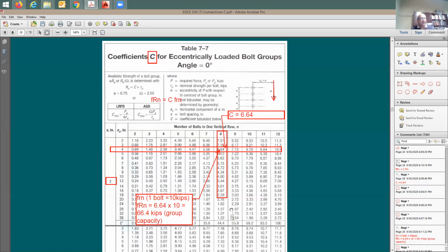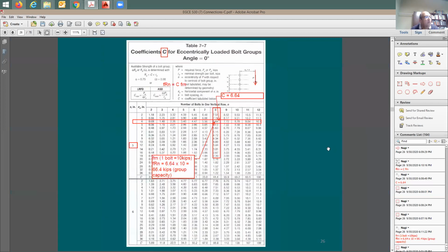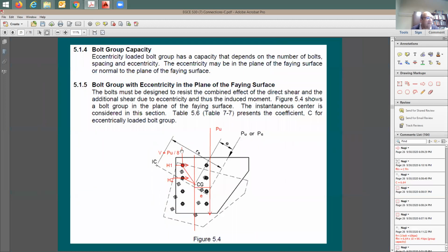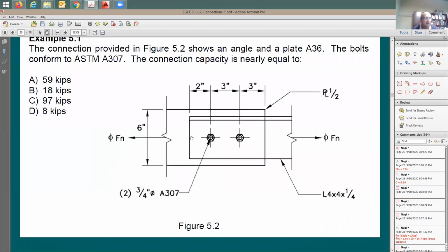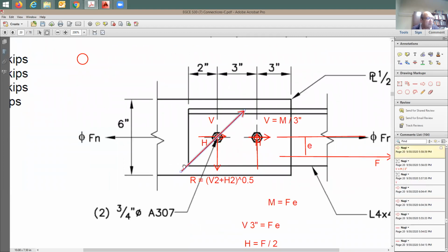Now I guess I understand why they call this the number of equivalent bolts, right? Great. This should be very helpful, especially when you have two rows of bolts and you have the steel bolt. It's going to be so simple. Now I'm trying to compare what happens here to this number of equivalent bolts when I'm talking about this discussion about vertical force, horizontal force, and find out the result and compare it with phi r_n for just one bolt. So I'm going to go back to my analysis that I was working on. Also, I need to flip this here for the applied force, right? I guess I should do this.